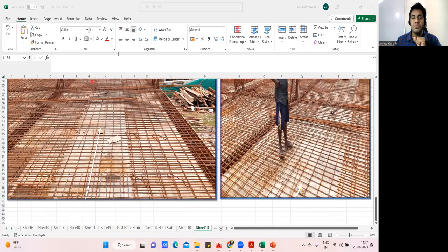It's very simple. We know that if I ask you to plot the bending moment diagram of this beam and slab junction, you have a negative bending moment, then you have a positive bending moment, then again you get a negative bending moment, right? So you have a negative bending moment. That means you require a top steel. Now, if you don't give a top steel, what will happen? I mean, you are giving a top steel, but how do you give it? You should give the top steel with the help of the chair bar.